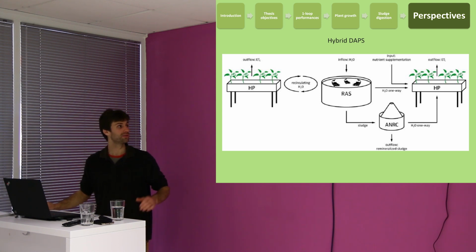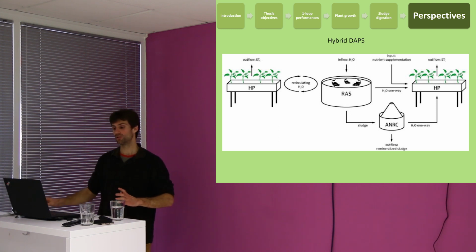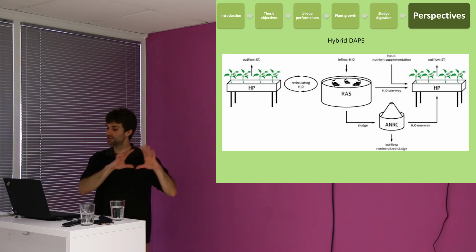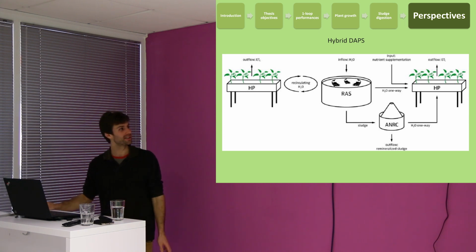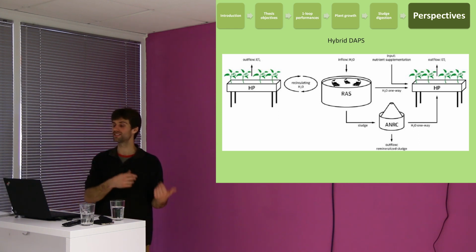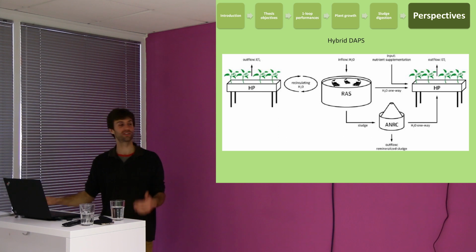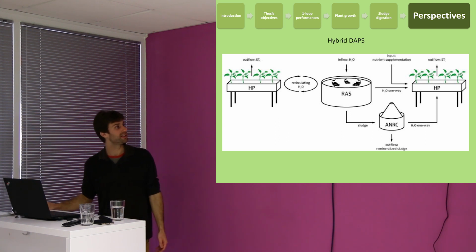So it's still good to have plants in the fish loop, but we saw that if we just do it like that, we lose a lot of nutrients. So it's also important to treat other effluent like the sludge and maybe all the water. I showed you that in our system, I exchange 5% a day and I lost all the nutrients. So all the water I remove even from this system, we should use it to grow plants.